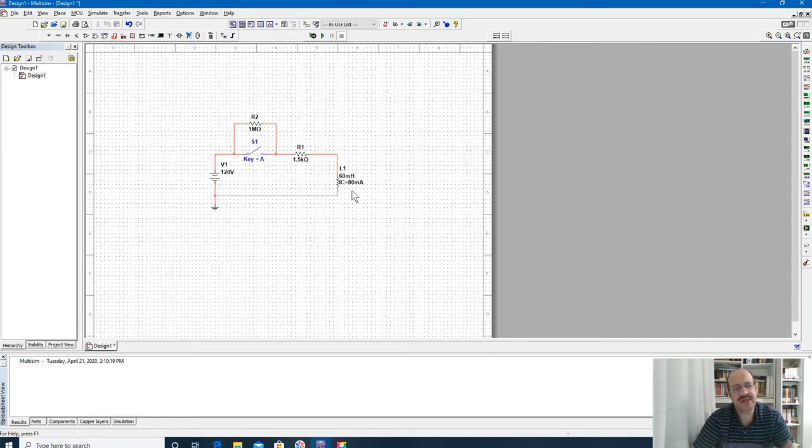So this is a case where the circuit has been working for a long time, the time constant has passed, and the current is 80 milliamp passing through it. So when the switch is open, this current will flow through these two resistors and will decay to zero. But at the beginning, this current will flow through the large resistor, and because the switch has been opened, you will see a very large voltage across the switch, which is actually across the large resistance of 1 mega ohm.